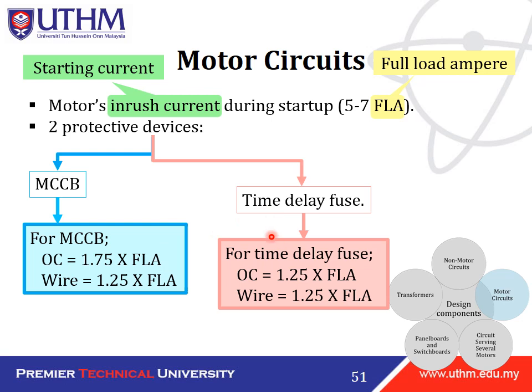Whereby for the time delay fuse, the equation for overcurrent and also wire is equal to 1.25 times the full load ampere. So this is the note: OC is for overcurrent, wire is for cable.